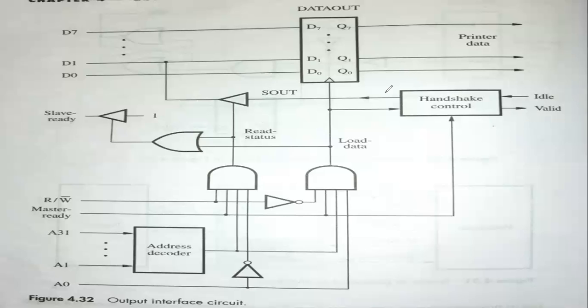Now we'll go through the working principle of this figure. The printer is available here somewhere, and it is right now available for printing the content, so it raises the signal called idle. The controller receives this input, along with 2 more inputs available here: 1, 2, and 3. By consuming a total of 3 different inputs, this controller will generate the S out signal equal to 1. That S out signal will be transferred towards the processor using line D1.